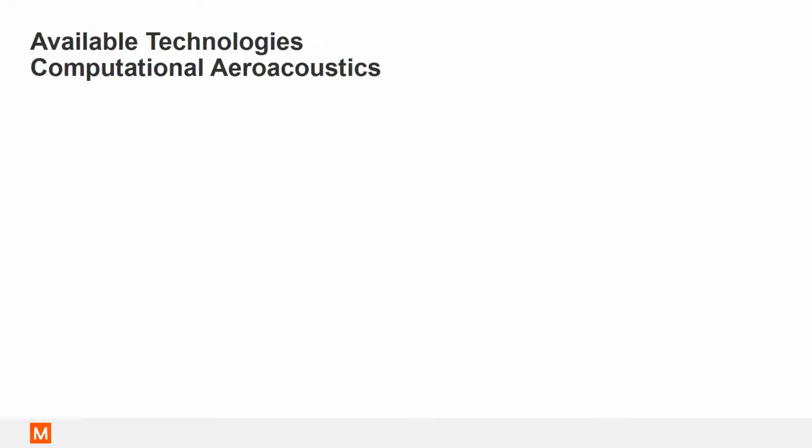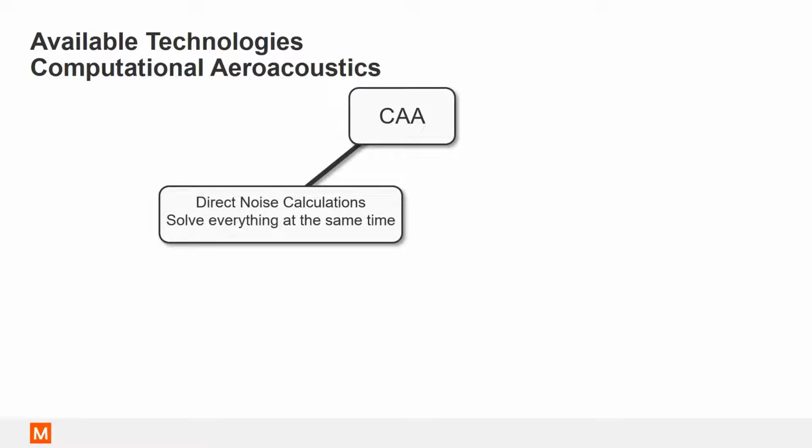All right. So the first method of resolving an acoustic problem would be the direct noise method. Now, it's an approach that requires solving the entire flow field for the full unsteady simulation. There are very few modeling assumptions and less work to set it up. Now, this can be done within STAR-CCM+. It requires a high numerical resolution to capture the spatial and transient effects of the acoustic pressure perturbation. It requires unsteady compressible CFD and turbulence models such as DES or LES.